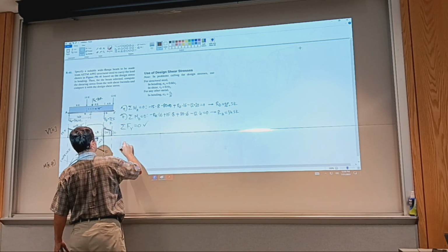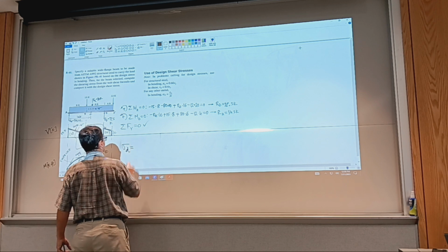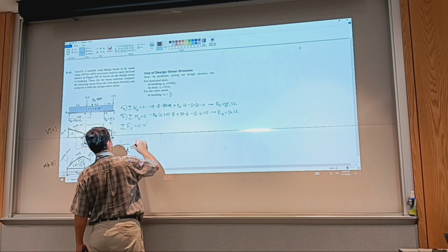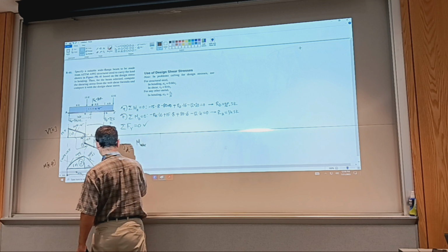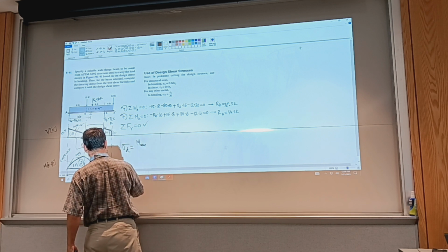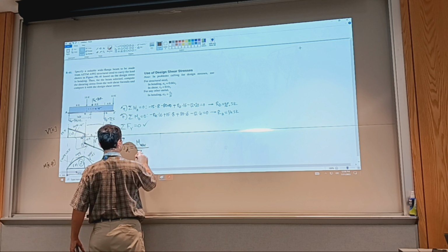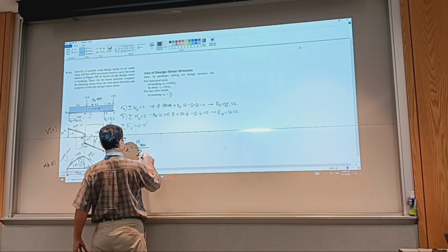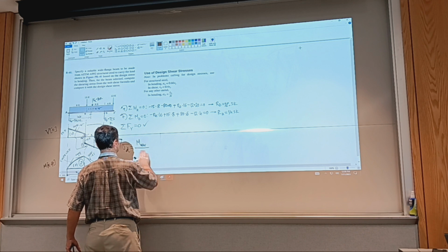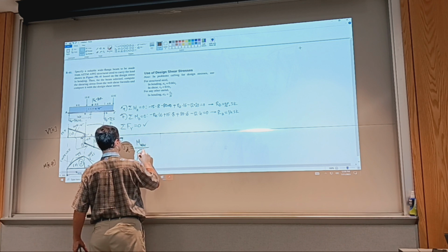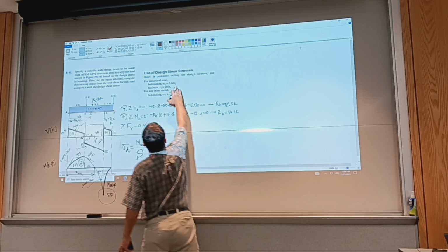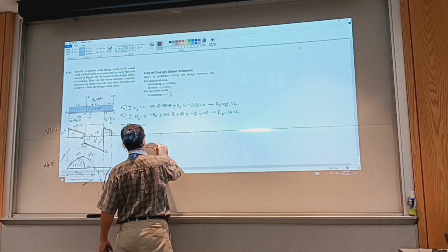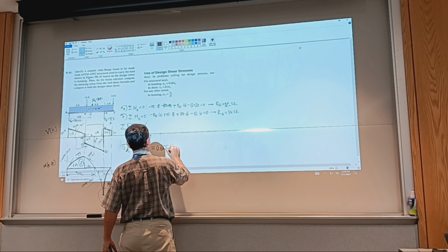So we need to calculate design stress that is due to bending. So I have M will be M max, which is this one, M max, divided by the section modulus. We're not doing twisting. And the design stress is going to be 0.66 of SY.